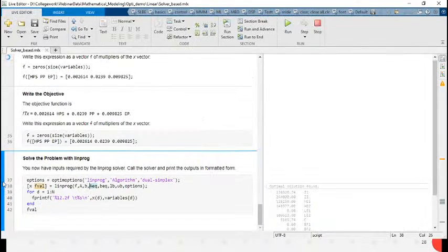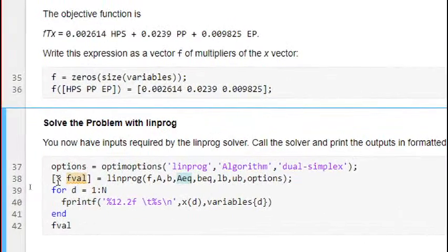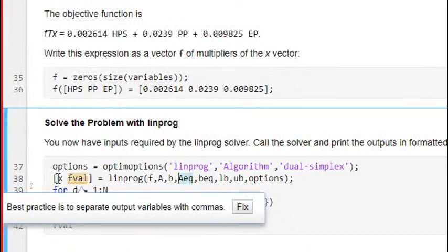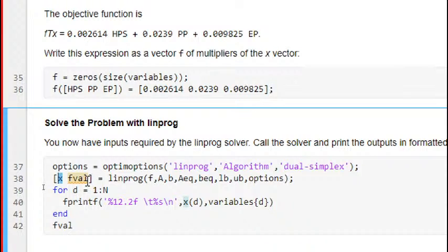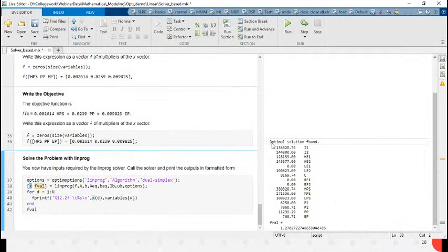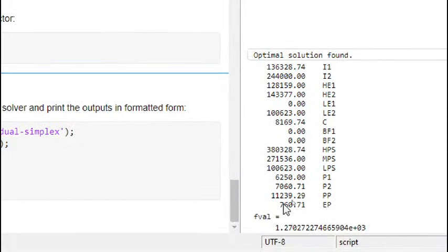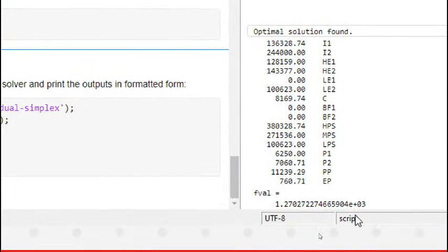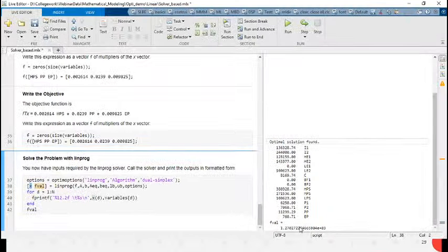Once we run this, we will get the optimized parameter values x and the minimum value. So you see these are the optimized parameter values, and this is the minimum value of the function. This is the same output we got in the problem based also, and the same output we are getting in the solver based. So if I compare both for this problem, I think problem based was easier, right? If you have fewer parameters, then go for the solver based. If you have so many parameters, then go for the problem based.